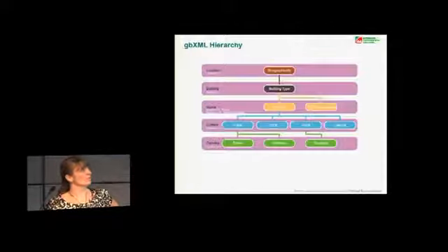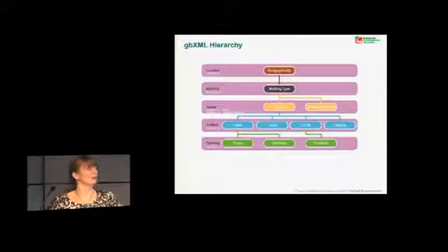We have rooms themselves, which is obviously critical. For analysis, we need bound volumes, and this is going to be key. For those of you that have been looking at the integration already, you'll know there are certain rules to follow to get those rooms to come across, which you can then perform your analysis on. If the rooms don't import for whatever reason, that creates an issue, because then we've effectively got a hole or a gap in the model. When we run analysis on that, the room adjacent to that hole sees it as an external zone, if you like, which will then affect energy flows through the wall that separates the two. So rooms are critical.